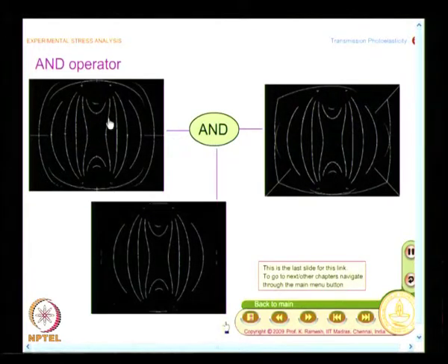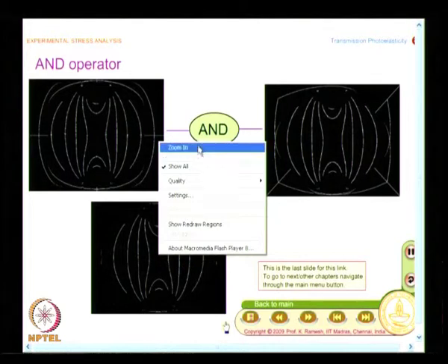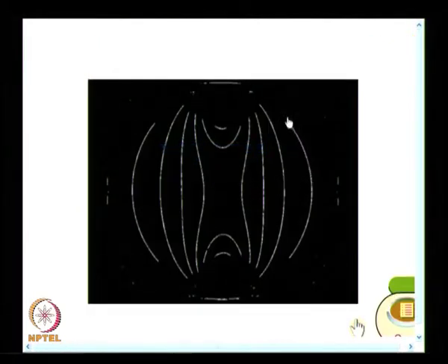So, I have this 0 degree 90 degree scan image, and the 45 degree 135 degree scan image, and I finally get the skeleton as good as this. You see only the fringe in the area where you have seen the fringes, and of course, the information in the stress concentration zone is lost, which was not there even in your edge detected image. Even when you had the edge detected image, you did not have fringes in the stress concentration zone. And how to circumvent this?